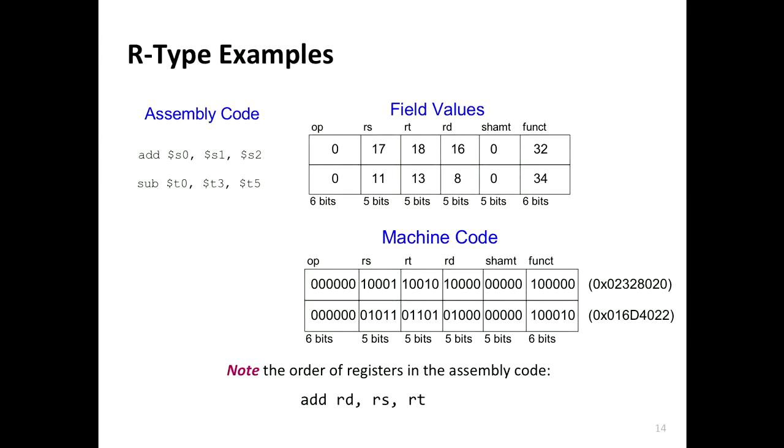Which is, what do we call it? Register selector. It's fantastic. It's addresses to exactly specify registers, right? So you need addresses. Let me call it A. What else do you need? Is one address enough? You need 3? Great. So you need address of RD, address of RS, and you need address of RT.